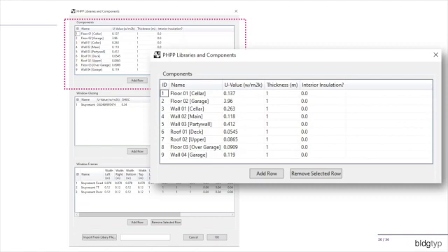I'm trained as an architect, and I like pictures. I don't like lists of numbers. So when I calculate U-values for walls, I like to have a picture of the wall to show me the studs and the spacing and the thicknesses. I find it so much easier to do all of those calculations outside of PHPP or outside of Rhino and calculate just a total U value. So for us, this works awesome. We can just take those U values and bring them right in. I totally recognize, though, that if you're using the PHPP constructors, this is not great.